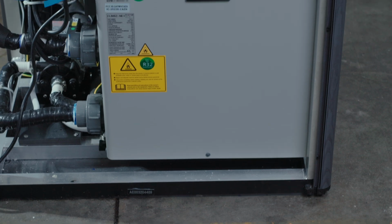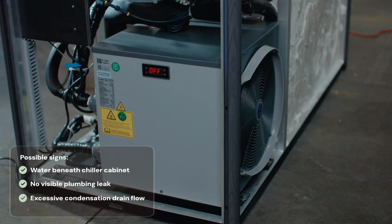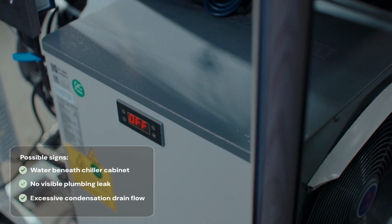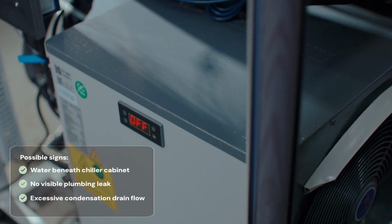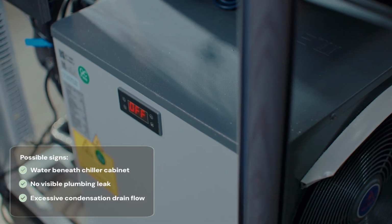If no external plumbing leaks are found, inspect the Balboa Chiller assembly itself. Internal chiller leaks may present as water dripping directly from inside the chiller cabinet or pooling beneath the unit without visible leakage from hose connections or unions.